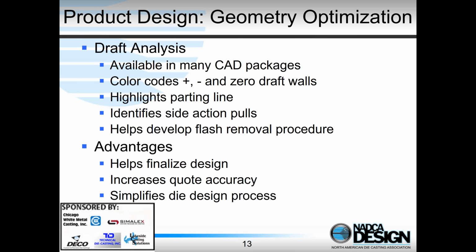And so it's very helpful for design people such as you to do this kind of draft analysis even before talking to the die caster, so you can get an idea of what features are going to require drafts and therefore how the tool is going to be built. And that's going to help simplify the die design process.